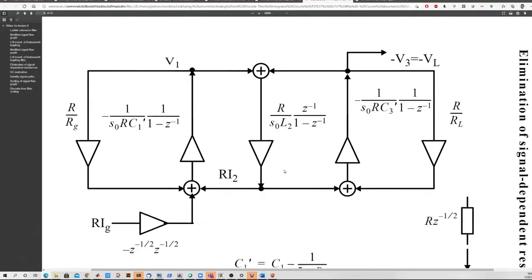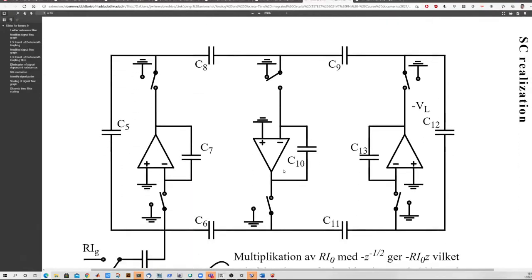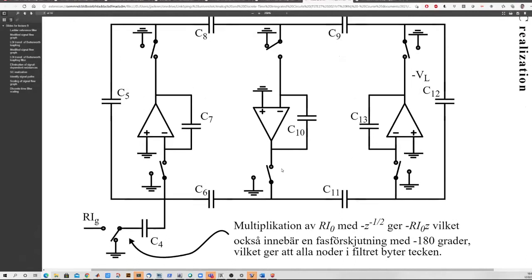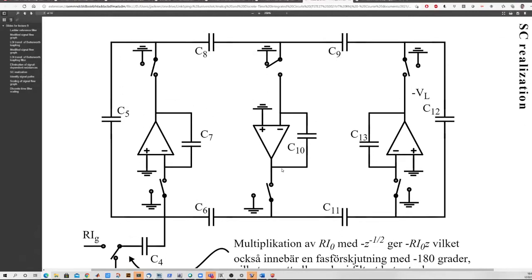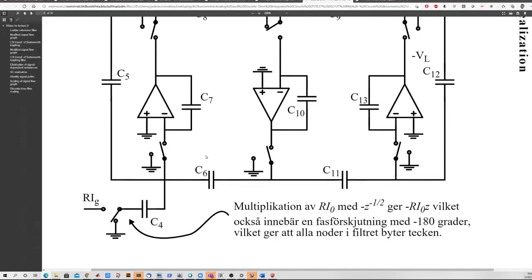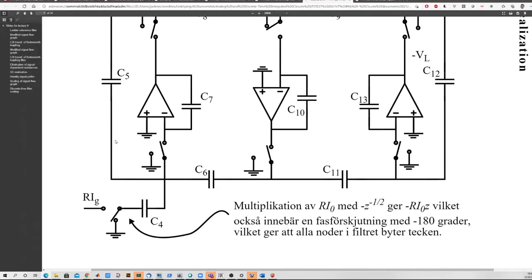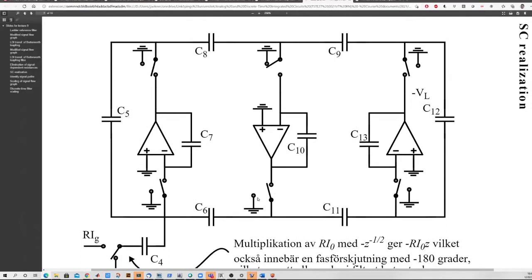So if I go down here, just to show you the resulting circuit, essentially this guy. So not too complicated, to be honest. It looks pretty straightforward. So I just taken my accumulator with a fixed capacitor across here with a certain C7. And then I have 3 inputs, C5, C4, and C6. And they are then switched accordingly.